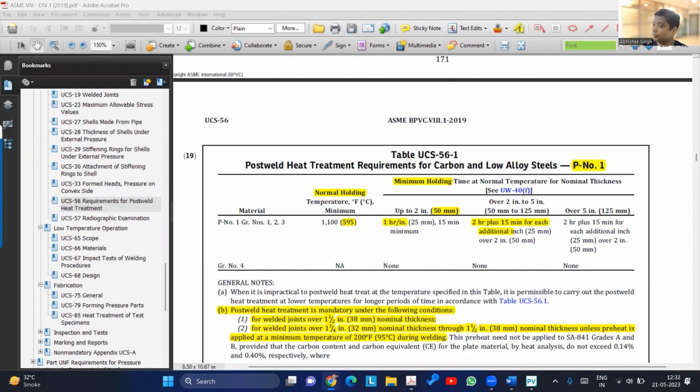Total and the percentage of that. If I have a 1 meter weld, I'll be testing 850 mm of that, if 85% is the requirement.